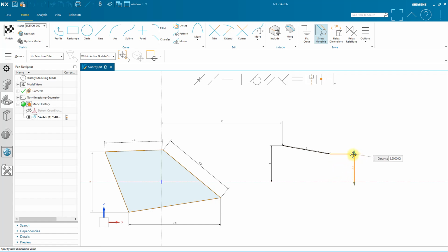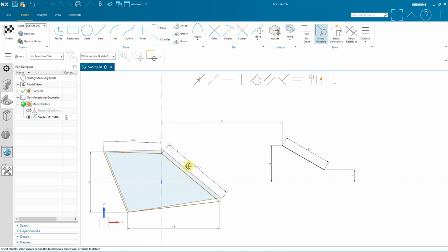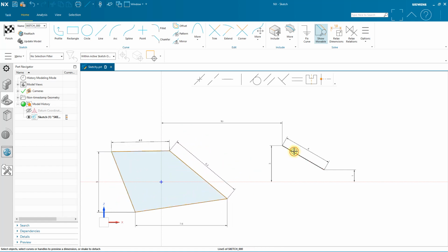But then I also want to define this endpoint here. And once I define this endpoint, let's say 1, you'll notice that instead of this brown movable color, where I can move this thing around wherever I want, it's this black color, and I can click, hold, and drag on it, and it doesn't go anywhere. It has these persistent dimensions that keep it fixed in space within the environment. And so this line, being black, is the fully defined object color.